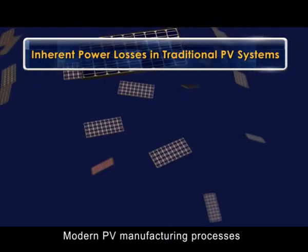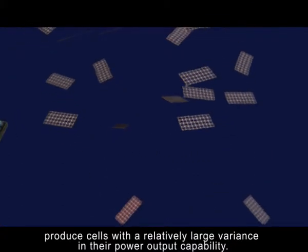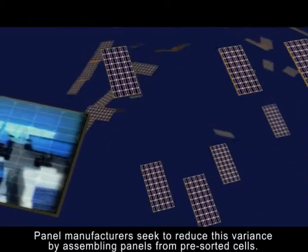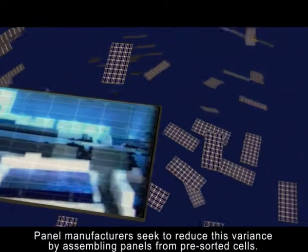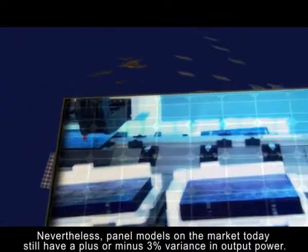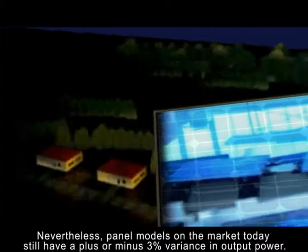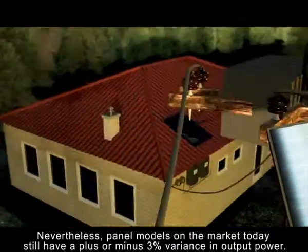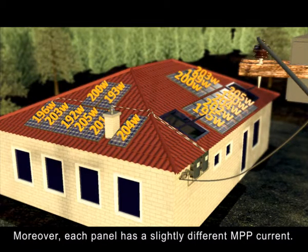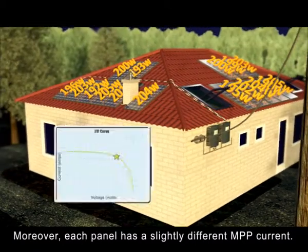Modern PV manufacturing processes produce cells with a relatively large variance in their power output capability. Panel manufacturers seek to reduce this variance by assembling panels from pre-sorted cells. Nevertheless, panel models on the market today still have a plus or minus 3% variance in output power. Moreover, each panel has a slightly different MPP current.